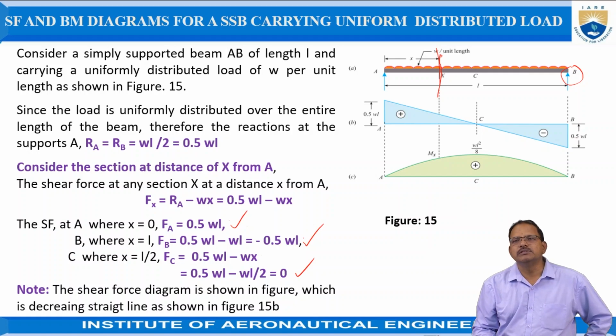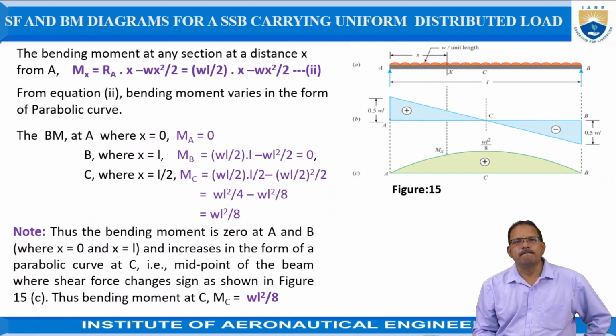Since the shear force is increasing or decreasing with respect to the distance from the free ends, all the points should be joined by using straight lines, or in other words, should follow the straight line law.